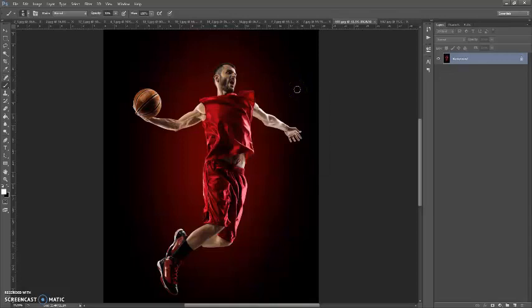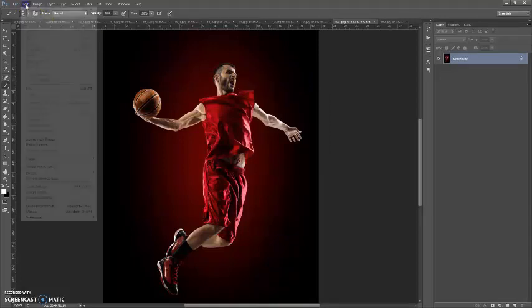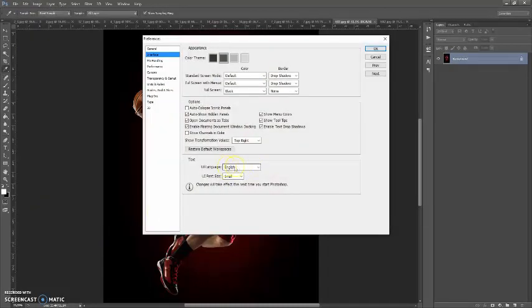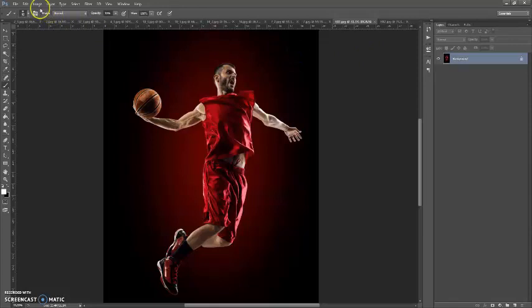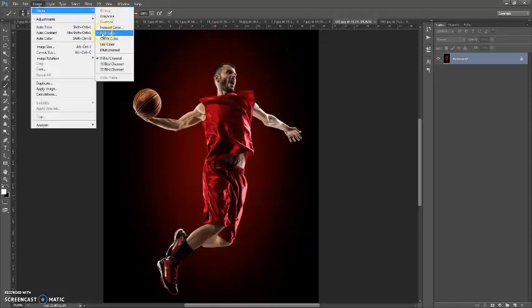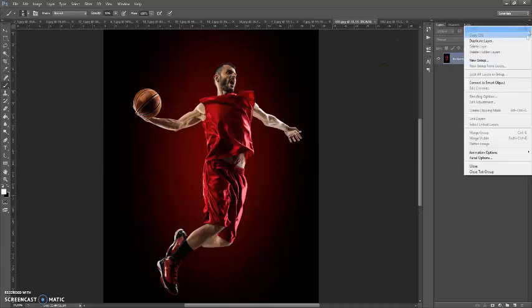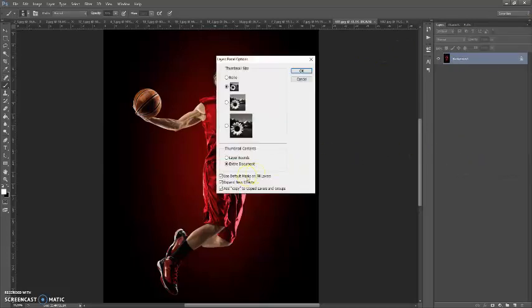Okay, and before your session you need to do these steps. First step, make sure that you're using the English version of Photoshop, and if you use a version with another language, watch the video on how to change language, the link is under this video. Second step, go to Image, Mode and check RGB color and 8-bit channel. And last step, just for CS5 and higher versions, click on the menu icon at the right, select Panel Options and check Add Copy to Copied Layers and Groups.